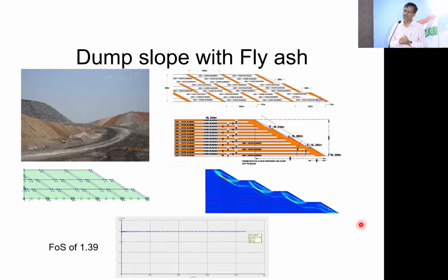No. Even if I get whatever the software or material is there, what he said is, Dr. Panda is correct. Anything new that you are doing has to be monitored. In the American standard, any geotechnical exploration consists of 4 parts: desktop, reconnaissance, detail and post construction. But here in India, we don't do any post construction. Ho gaya, bas. We never consider whether it is performing as per the design or not.